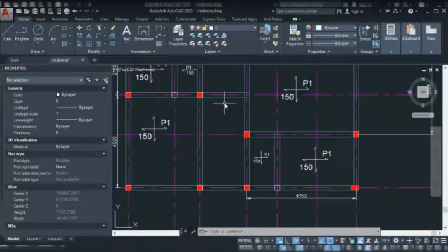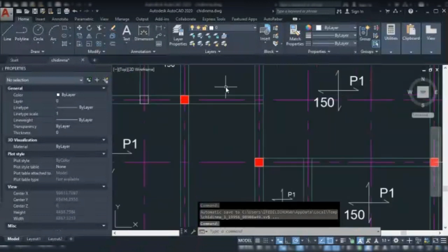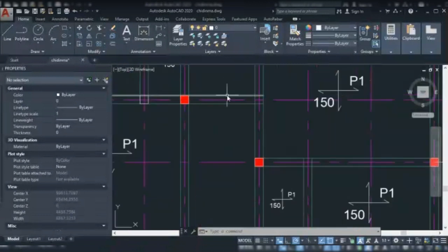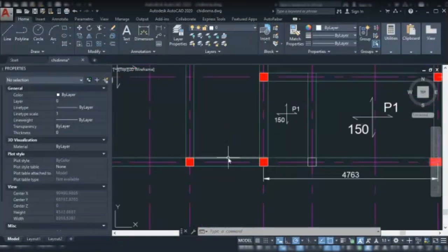All right. So why I brought out the beam: I want this beam to carry my staircase. So this is called a stringer beam, like I said. I'll have my landing at this place, okay? Remember what we measured, about 3,913, and the total length of our going is 3,000.